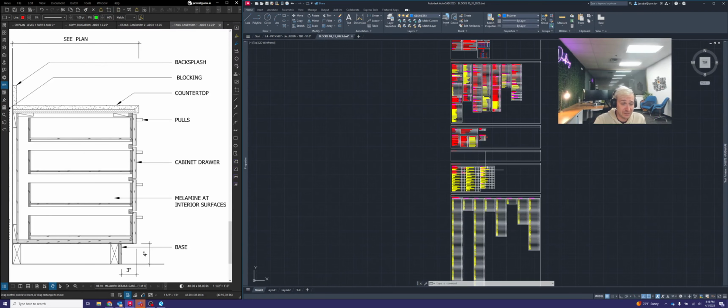All right. Now, there is a grip point that's predefined up here at the top. That's going to line up with the top corner of your drawer front. Should give you a 4-inch gap from the top of that drawer to the underside of your cab there. And then just like any other drawer, you do want to make sure that you're within 2 inches of the back. So I need to adjust the depth of this here. So I'm at least a maximum of 2 inches from the back.